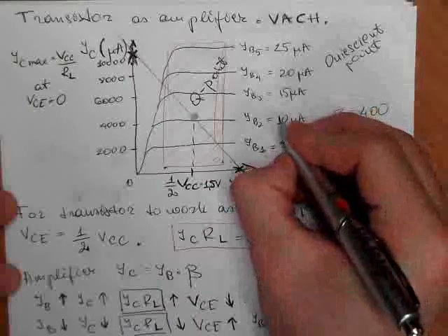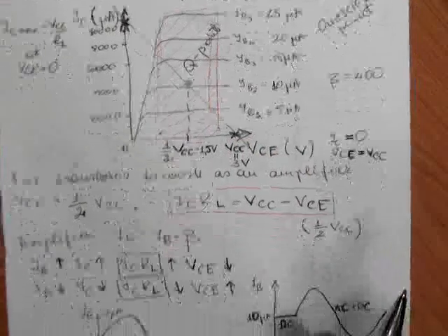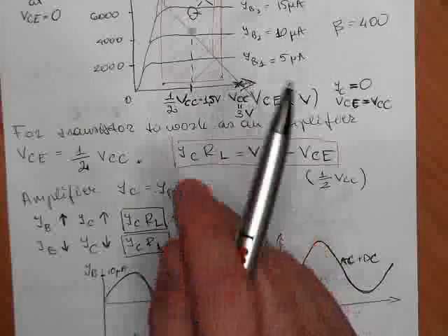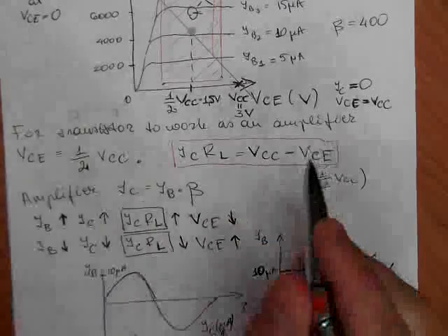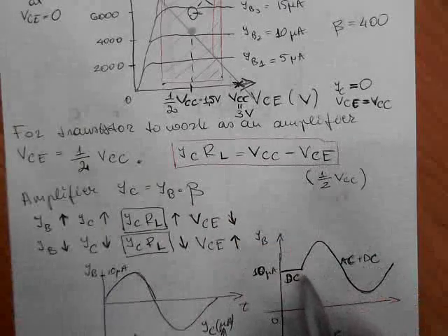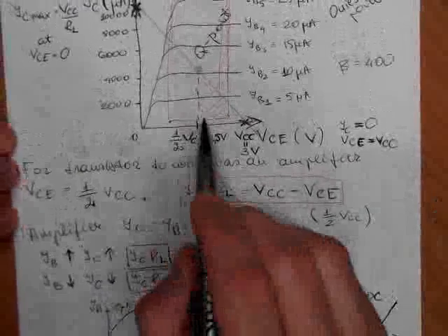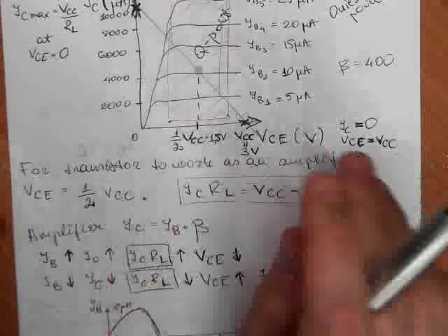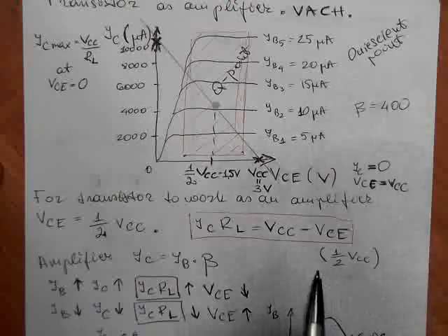You develop AC current on this DC current, so as to get positive and negative AC swings on this base current, and to produce collector current increasing or decreasing. Okay, so this was very complex theory behind the transistor as an amplifier, the transistor volt-ampere characteristic, because you see a lot is involved here.